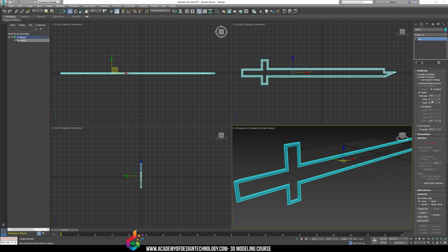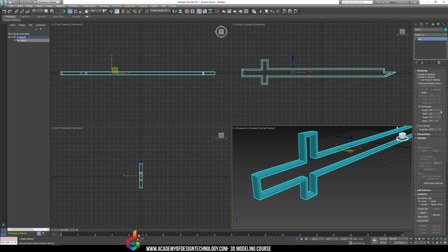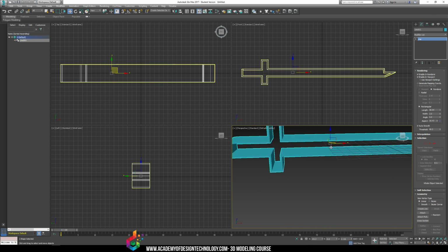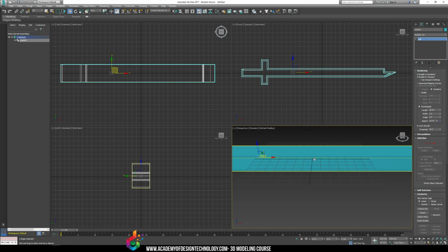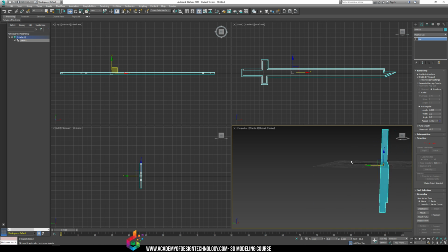So we can change a whole bunch of things really quick like this, or we can change it to rectangular. Now rectangular gives it length, width, and an angle, and you can see that we can actually create a whole bunch of shapes using this. So if I change the length here, there you go. So that's good for creating outlines.